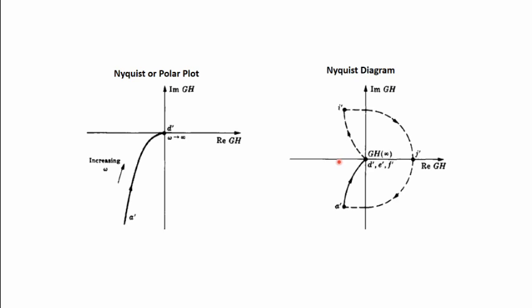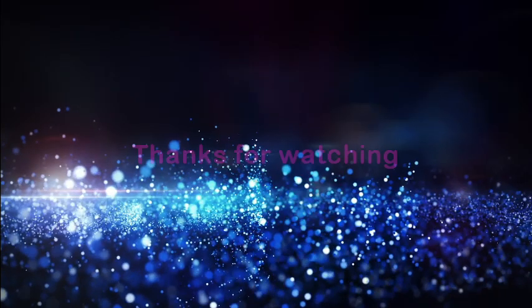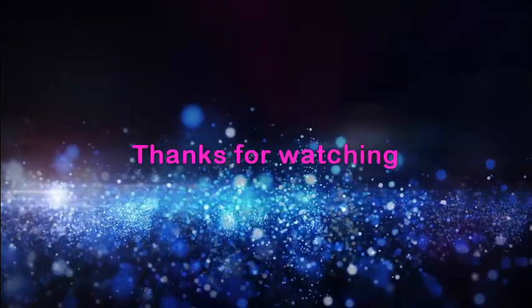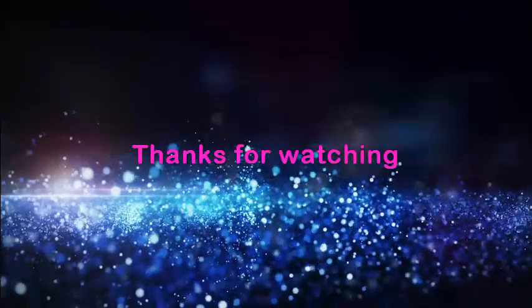Because this is a minimum phase system, it does not have any poles on the right half, and the closed loop path does not encircle the minus 1 j0 point. That is why the system is stable.